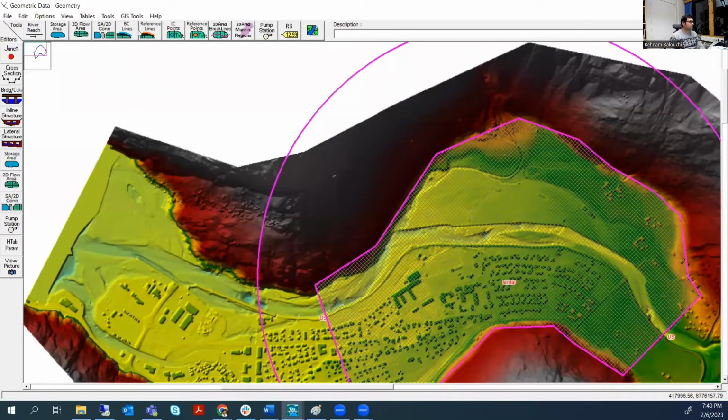So what should we do for fixing this problem? We should have break lines, and I recommend making this at the starting point of defining the mesh. I just do it now because I want you to first learn what the difference is and what your options are. So we are going to the 2D break lines, and I just make it so fast here, but you should have details on that and put time into a good definition.